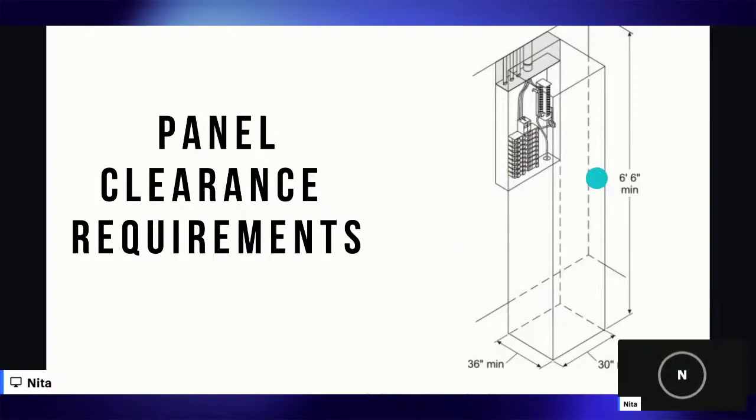So this is basically talking about if you have stuff in and around your panel board, your enclosure, your box, as you guys would call it. The area that's above and below is only for electrical equipment. You shouldn't have any plumbing pipes or any HVAC pipes. You need to be able to reach this without having to climb or use a ladder, without moving items. That's what we're getting at with these clearance requirements. If it is blocked or hidden in any way, that is a reportable defect.